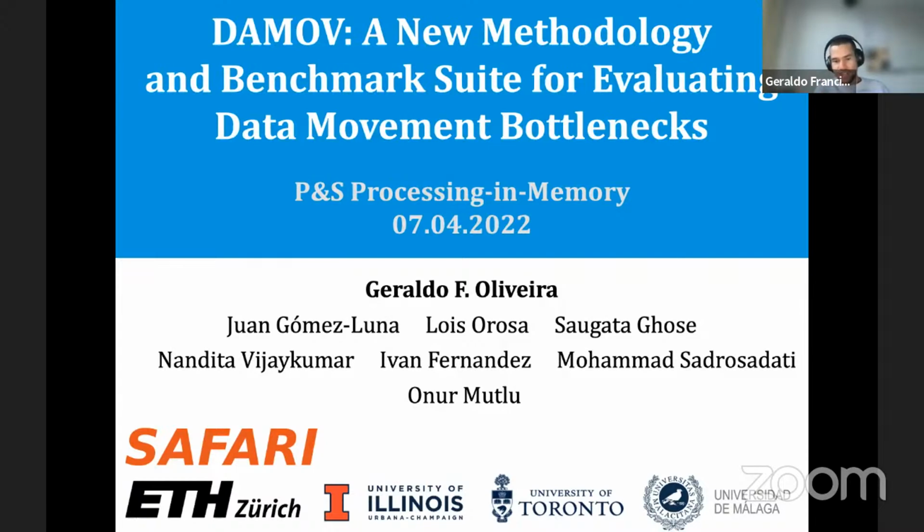And there is, of course, some caching system being employed to figure out if a particular piece of data can be accessed or not by a particular PIM core, because employing the same coherence protocols that we have in the CPU, like directory-based or snooping-based, in the NDP system is quite costly because of the area limitation of designing a network and so on. So there are these two problems, both from the host to the PIM cores and also across PIM systems, the PIM cores themselves.